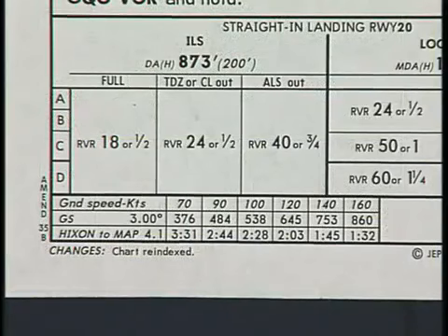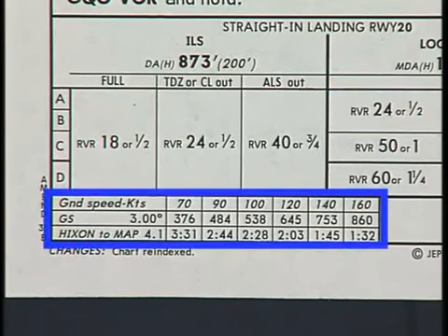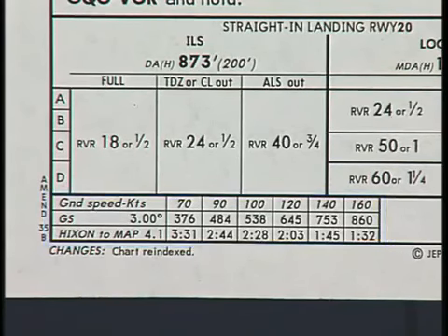The last section on the classic chart format is the conversion table. This table provides information about the descent rate and timing, depending on the type of approach. Both chart formats show the same type of information, but in the briefing strip format, the conversion chart is located above the minimum section.